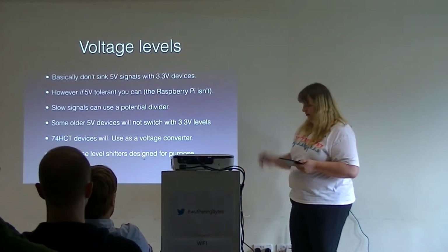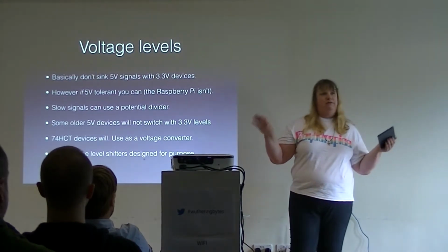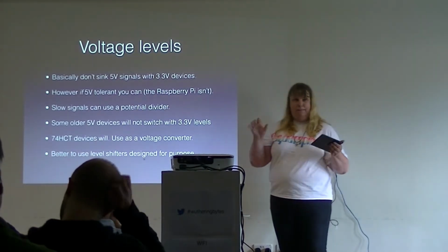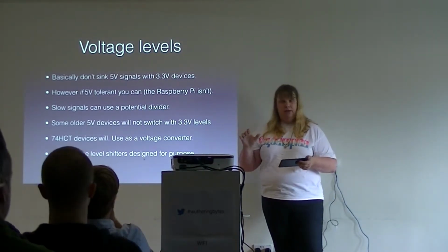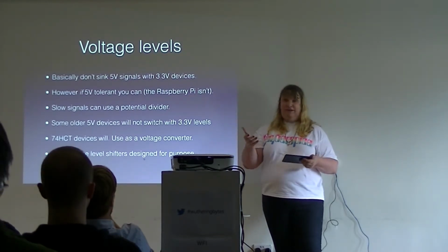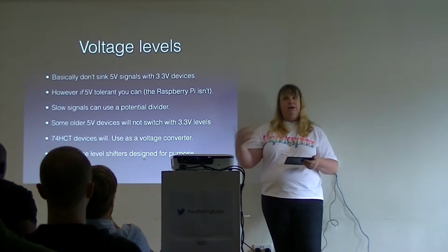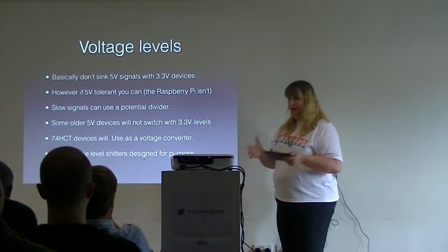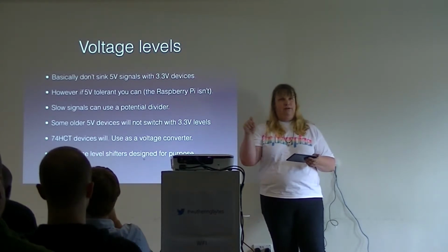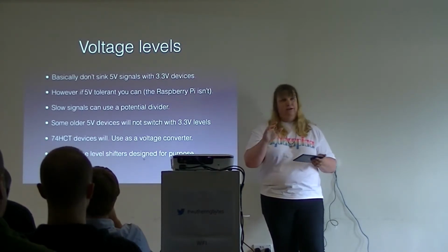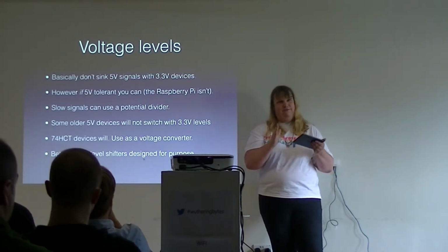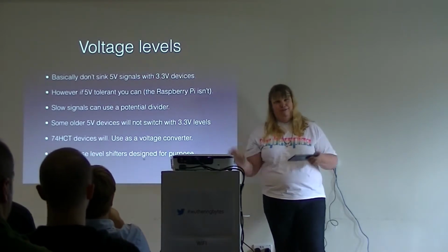There are a whole bunch of different chips called TTL chips, transistor-transistor logic, and they're basic logic gates. And every now and then they bring out new versions of effectively the same packages using new technology. They're all originally numbered like 7400, 7420 and so on. And gradually over the years, they've got more and more letters stuffed between the 74 and the digits afterwards.